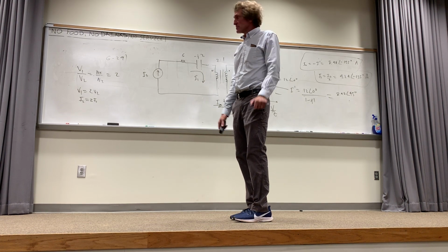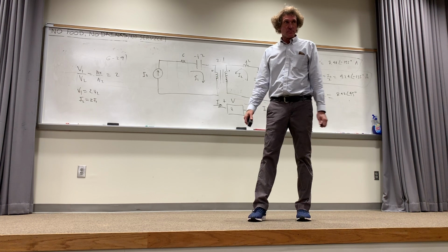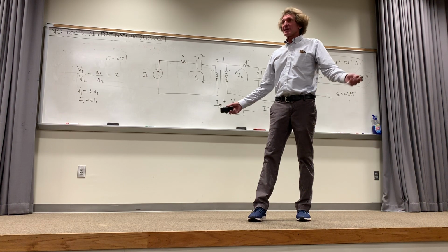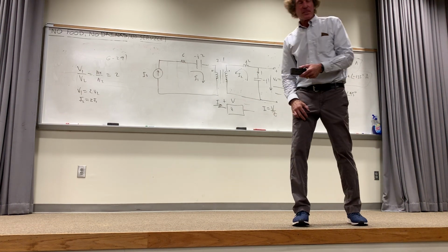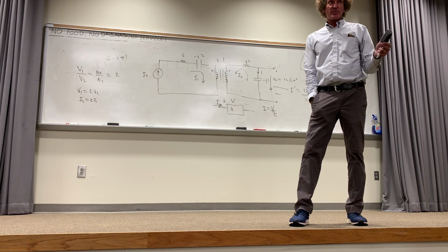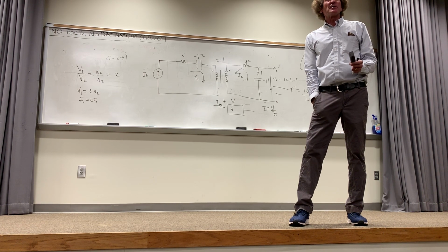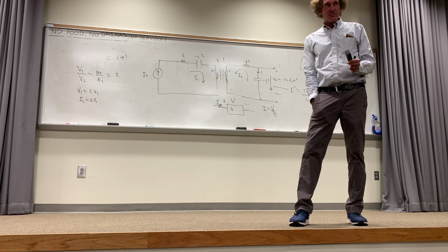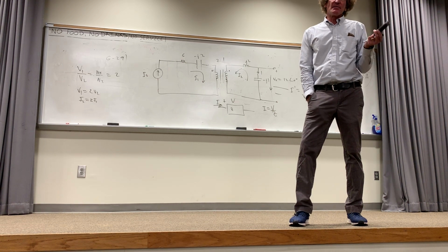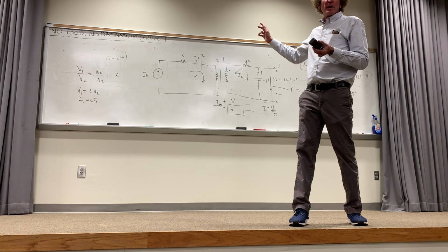Yes. The reason why we don't have to use any mutual inductances is that there is no mutual inductance. This is a transformer problem, not a coupled circuits problem. This is a transformer, it's turns ratios. What I didn't get to tell you, and that comes at the next lecture, is this. If they have very, very good coupling, then the mutual inductance is equal to the square root of L1 times L2 times a factor K. If K is equal to 1, and this is something you're going to have to take on faith, then in fact, you don't need to worry about a magnetically coupled circuit.